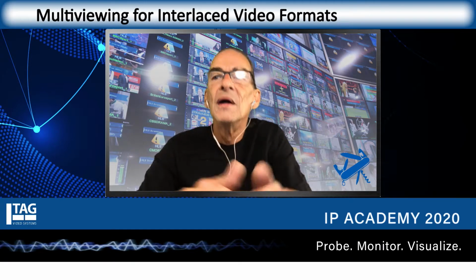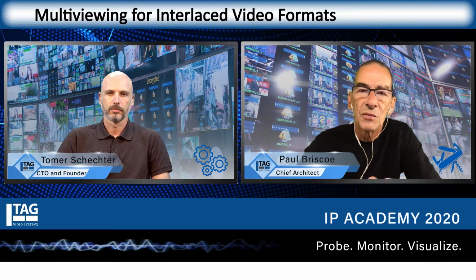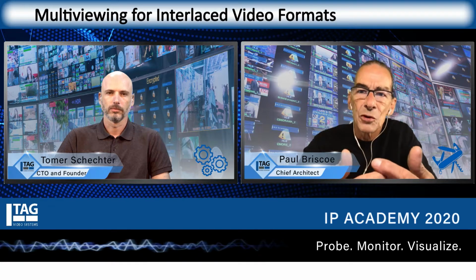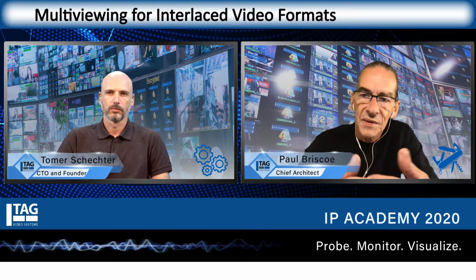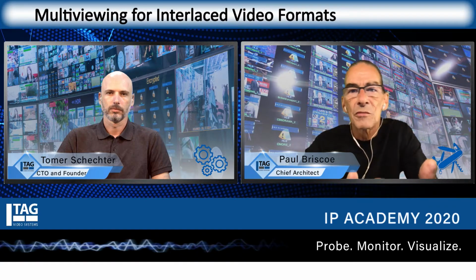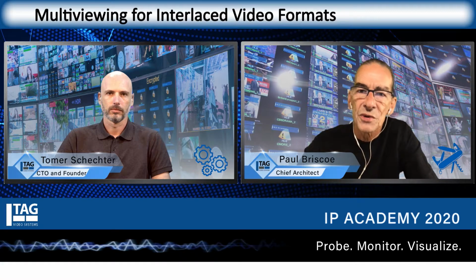lines 2, 4, and 6 would be scanned the second time around. We can now transmit a high enough frame rate that it exceeded the flicker threshold for the human visual system. So a 50 or 60 hertz flicker rate didn't produce flicker in the human visual system. And it would transfer motion because at this higher frame rate, the motion would be more fluid, even though the resolution would be lost vertically. But that loss of resolution is difficult to perceive by the human visual system. So it was a very neat trick to save bandwidth and actually enable high quality television, which in the day they called high definition TV, in a meaningful manner that could be transmitted in a reasonable amount of spectrum and so on.